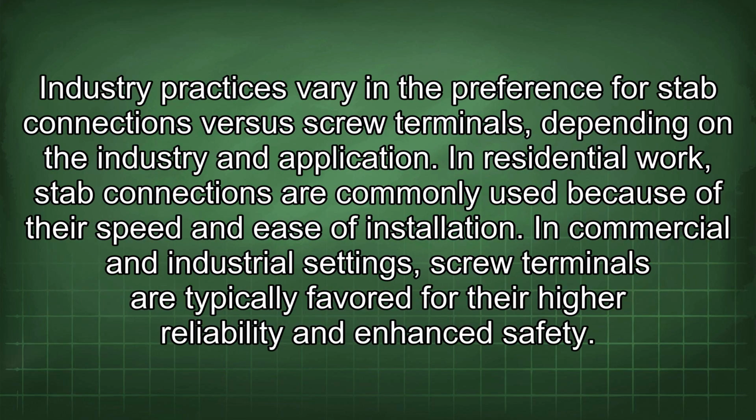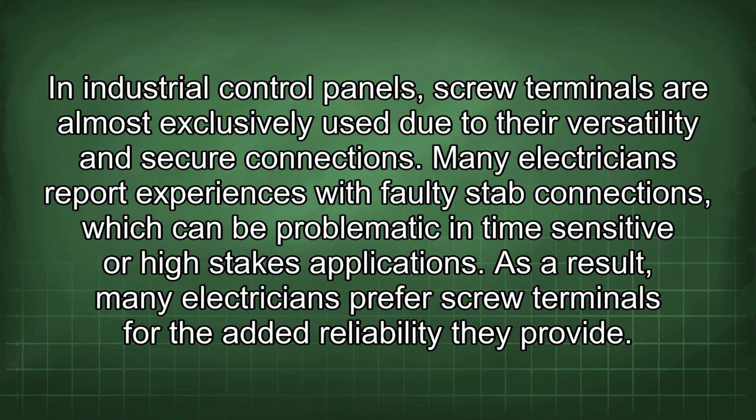Industry practices vary in the preference for stab connections versus screw terminals, depending on the industry and application. In residential work, stab connections are commonly used because of their speed and ease of installation. In commercial and industrial settings, screw terminals are typically favored for their higher reliability and enhanced safety. In industrial control panels, screw terminals are almost exclusively used due to their versatility and secure connections.